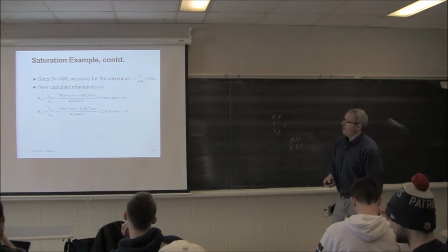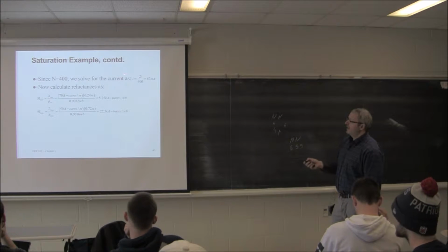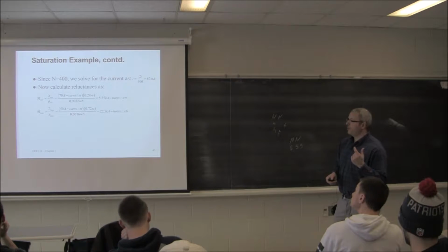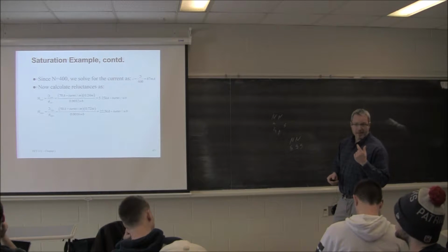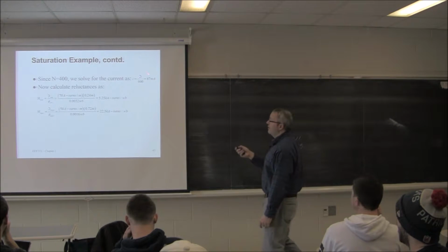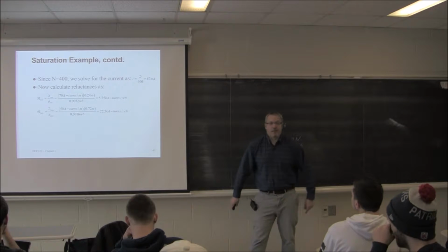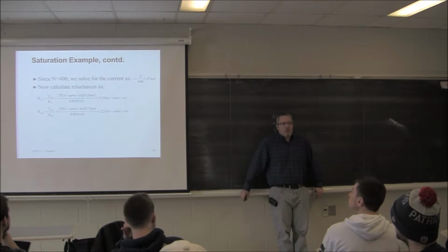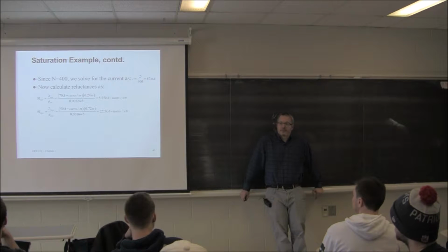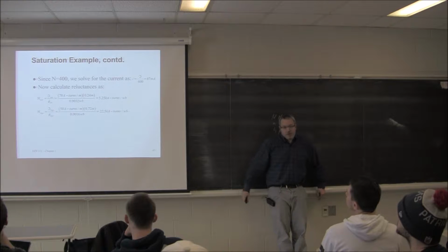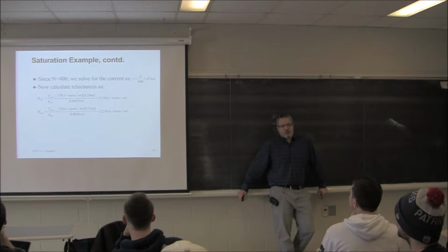So now I know what my voltage is. I solve for my current, so I only needed 32.8. For my magnetomotive force, I've got 400 turns, so I need 87 milliamps of current through that coil of wire to give me my 0.5 T. So there's two ways you can do it. You can either bump up the current or add more turns, whichever you want.